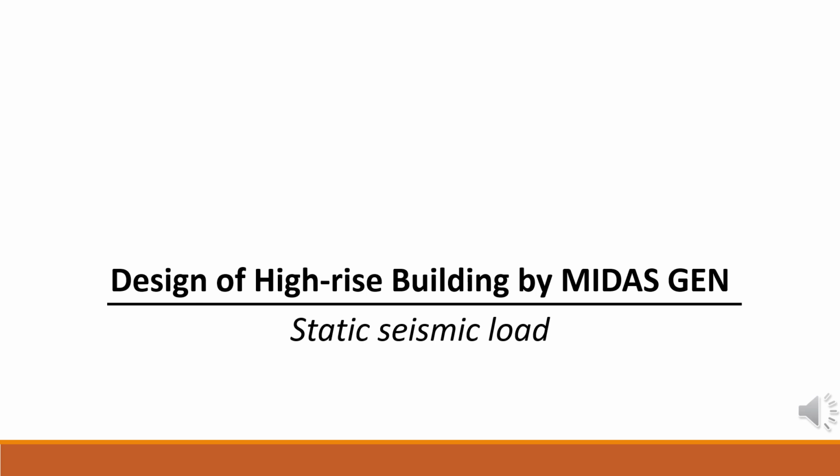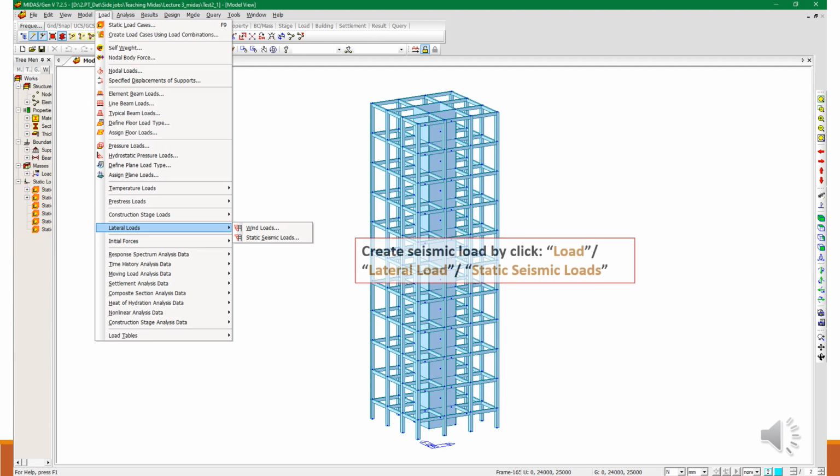Today, we will study about seismic load. Firstly, create seismic load by clicking Load, Lateral Load, Static Seismic Loads.